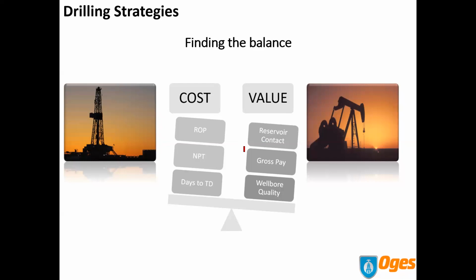So maximum reservoir contact is key, obviously. So if you have a directional well, you want to make sure that you're drilling within the reservoir and have maximum reservoir contact. Is critical for efficient hydrocarbons capture. And maximizing the ultimate recovery obviously is dependent on the wellbore quality.